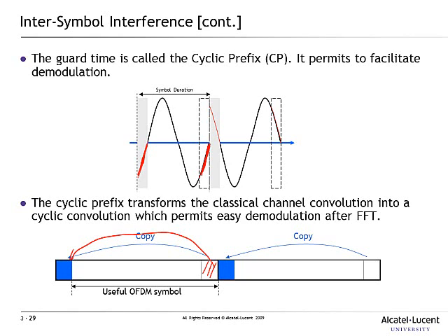This guard interval is also referred to as a cyclic prefix, and the cyclic prefix enables easier demodulation. What we do is we make a copy of the last part of a symbol and stick it in the front where the guard interval was going to be. This technique has been found to be quite useful in OFDMA to avoid the problem of intersymbol interference.